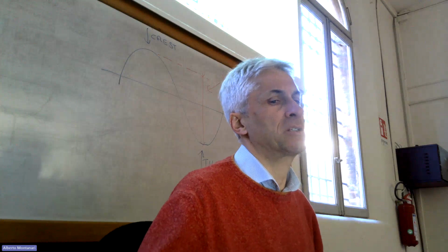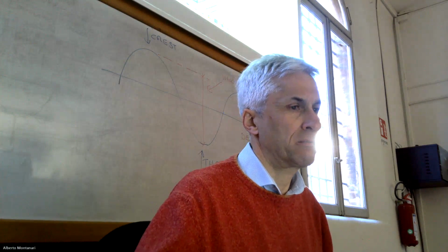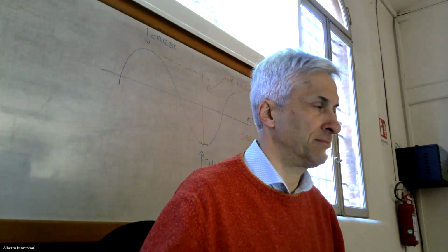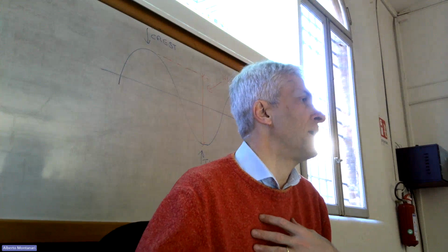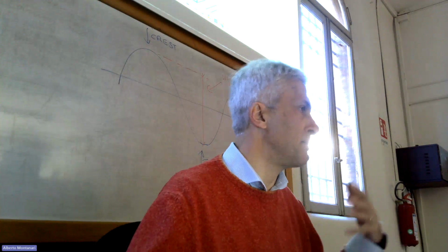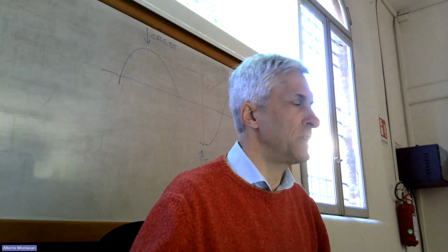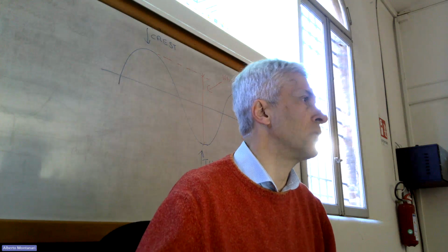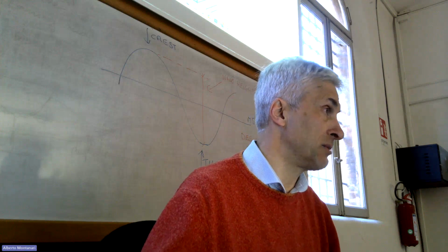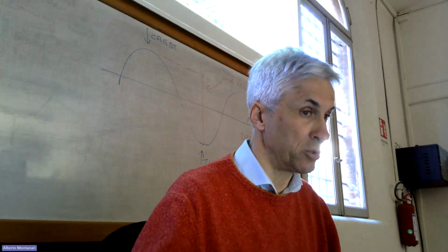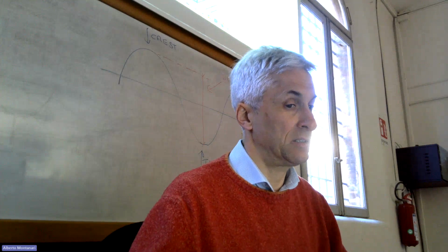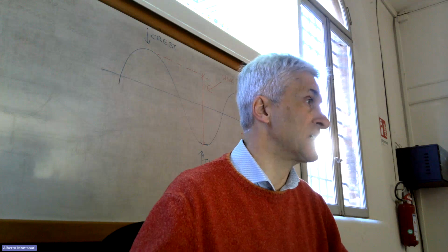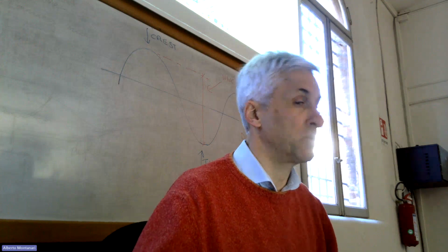So what we said is, okay, once the return period is assigned by guidelines or by my own determination, we can fit a probability distribution. I think Professor Archetti will mention or already mentioned to you the Gumbel distribution. Typically, we use the Gumbel distribution. And then we get an estimate of what we call the design wave.